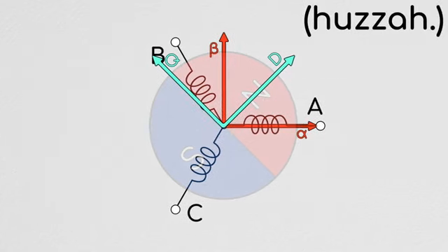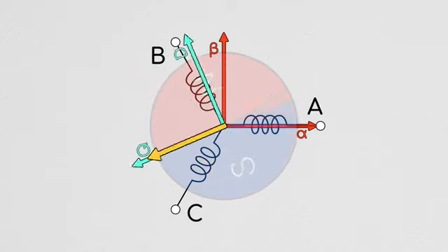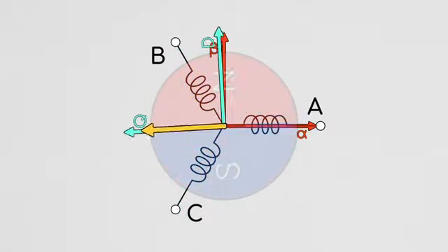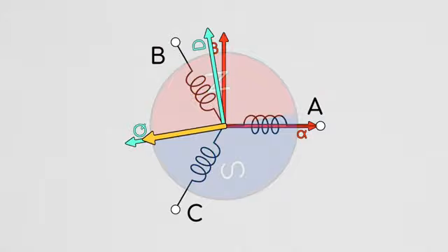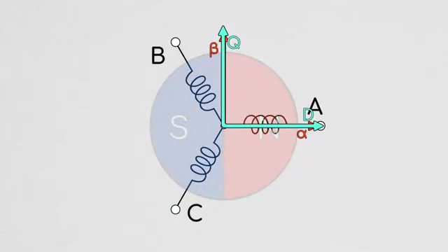Okay, so now we have these transformations and reference frames, so let's look at what the actual implications are. First of all, if we want to optimize the amount of torque we're getting per current in, which we usually do, we can say that at any time for a non-salient pole motor, we want our current to point strictly in the Q-axis direction. Note that if we're using a salient pole motor, the optimal direction depends on some other variables and will typically lead our Q-axis a little bit. I'll link a set of MIT class notes that talk about this in the description below for people who are curious. But to keep things simpler, let's presume we're using a non-salient pole motor, and let's run through our 6-block commutation scheme, again using this diagram.